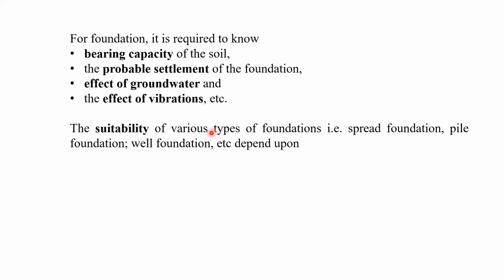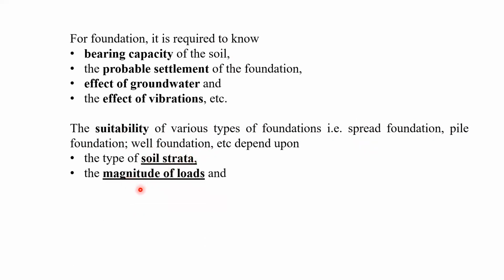See, the suitability of various types of foundation, like for example, a spread foundation, which comes under the shallow foundation, pile foundation is the deep foundation, well foundation is also a deep foundation, depends upon the type of soil strata, magnitude of loads, and the groundwater condition.